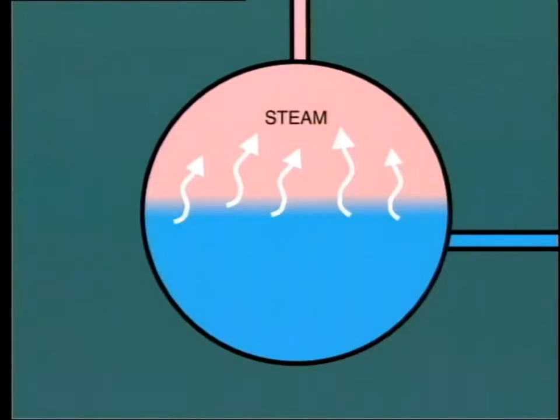As much as we try to provide perfectly pure water to the boiler, it is inevitable that some small quantity of contaminants do get through and concentrate in the boiler water as more and more steam is evaporated. Remember, as water evaporates into steam, the solids contained in the water remain behind, and this concentration increases as more and more steam evaporates.